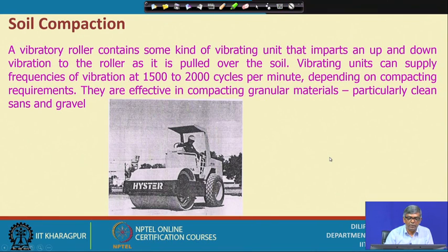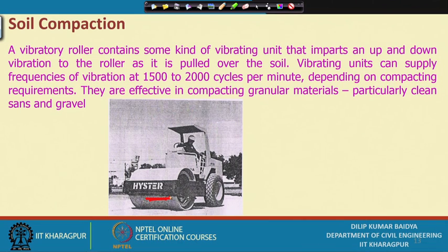Then there is another type of roller. As I have told, when it is a granular soil, compaction by weight alone is generally not that effective. So, if you can provide some sort of vibration along with this weight pressure, then it becomes effective. In this type of roller there is a moving element that also vibrates while moving. The vibration causes particle adjustment, and there is also pressure through the weight. These two together compact the soil nicely.